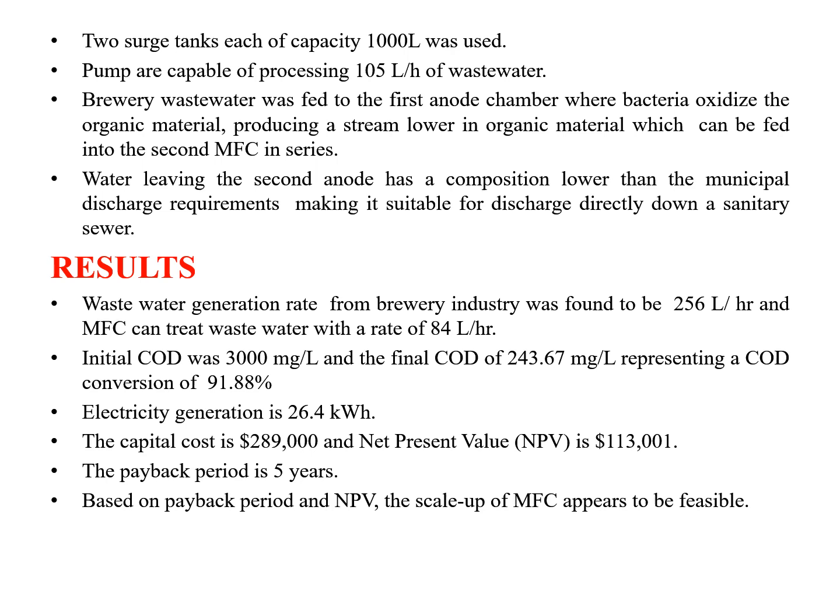Results: the wastewater generation rate from the brewery industry was found to be 256 liters per hour, and the MFC can treat wastewater at a rate of 84 liters per hour. Initial COD was 3000 mg per liter, and the final COD after treatment is found to be 243.67 mg per liter, which represents a COD conversion rate of 91.88%. Electricity generation is 26.4 kilowatt-hour.